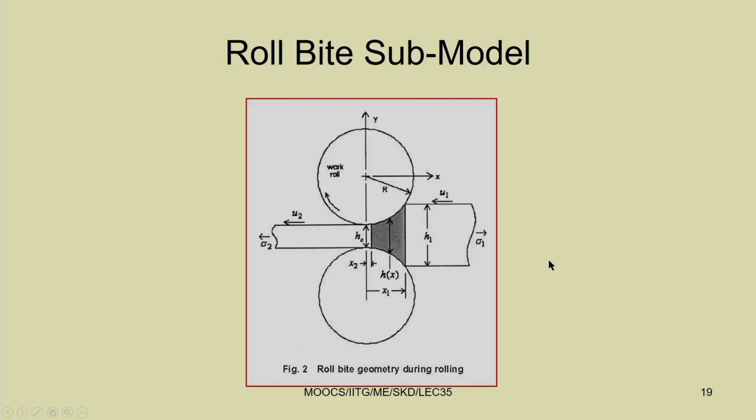So, then we can see the roll bite model. In the roll bite models we can consider the stress acting on the sheet. For example, let us take this is sigma 2, this is sigma 1. Due to this there is a tension, and u1 is the velocity on the inlet side, and u2 is the velocity of the strip on the outlet side.